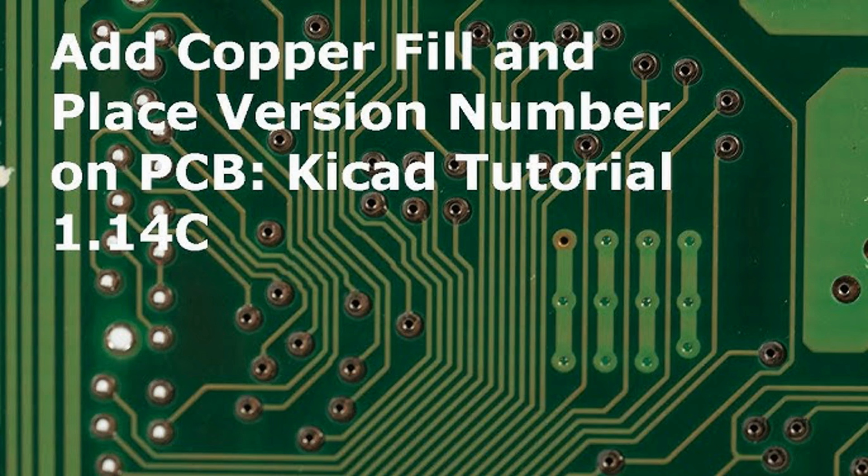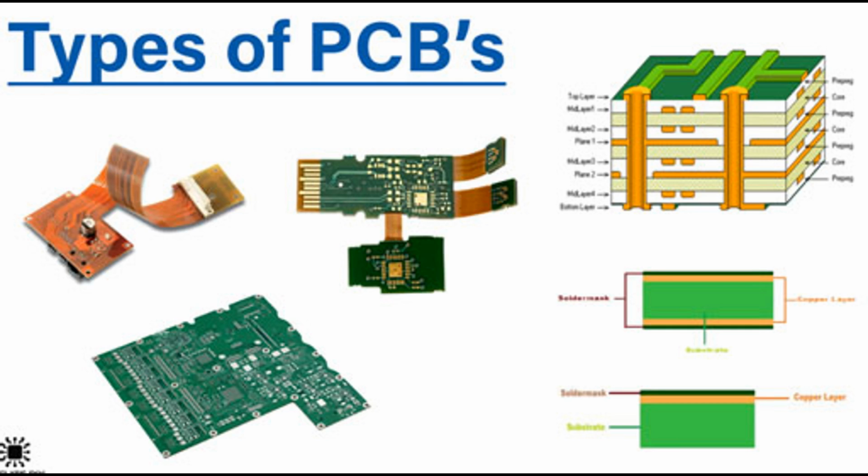Mechanical support. The substrate offers structural support to the PCB, ensuring that it maintains its shape and integrity. It helps protect the fragile components and conductive traces from physical damage or stress. Electrical insulation. Substrates are typically insulating materials that do not conduct electricity. This property is crucial because it prevents unintended electrical connections or short circuits between the various components and traces on the PCB.